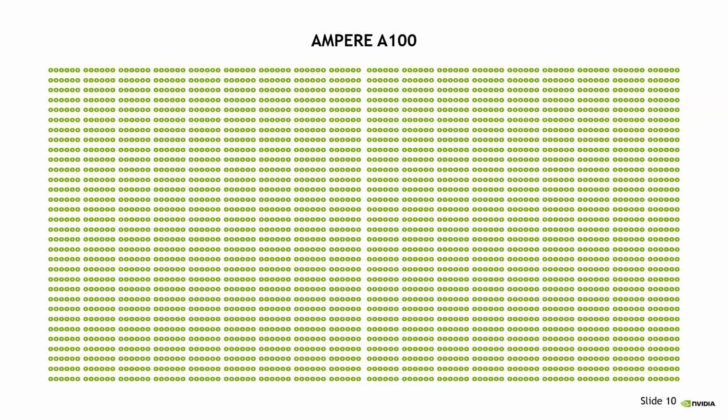Within a column, down a column, 32 dots here make up what they call a warp. And a warp of cores basically runs almost as what you would think of as an SSE lane, an AVX lane. This is actually underrepresented in that in a single instruction on an A100, you can have 64 threads, so double the height of this diagram, number of cores running every cycle.